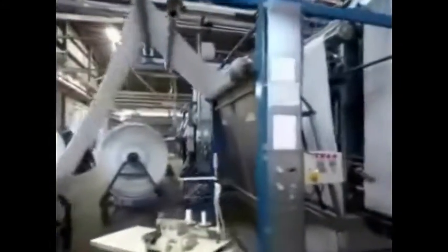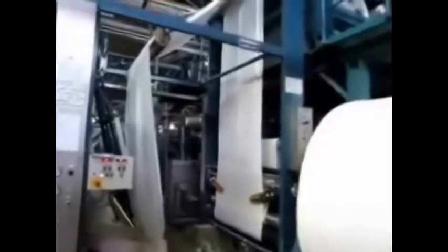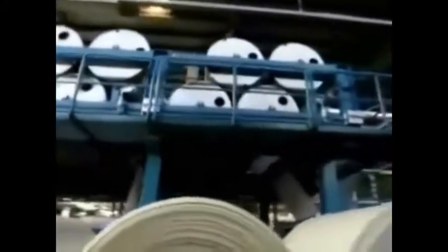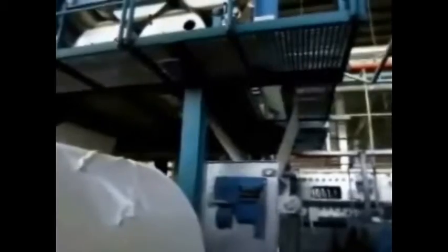The main purpose of this machine is to increase luster, increase the dye affinity, give dimensional stability and width control, and after mercerizing, the use of dyes is less. Usually 80% sodium hydroxide is used as the mercerizing chemical. This is a long length machine.